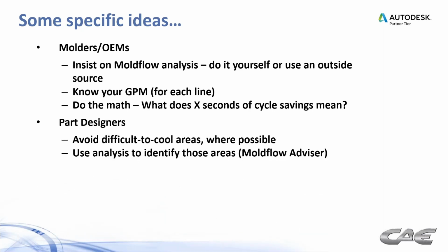For part designers, when you're designing your parts, avoid difficult to cool areas where you possibly can. Much of the problems that result on the manufacturing side for injection molding result from the part design itself. Follow those plastic part design 101 recommendations, and this is one of them for cooling.